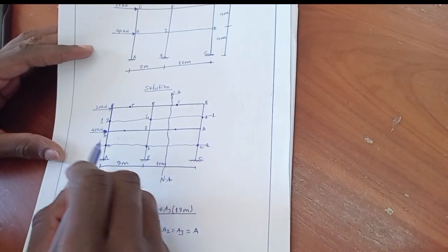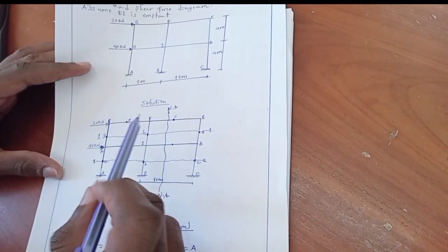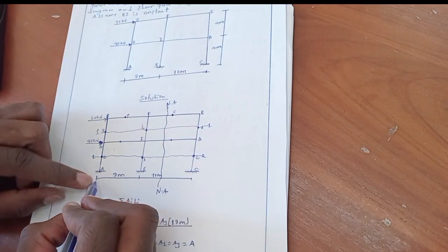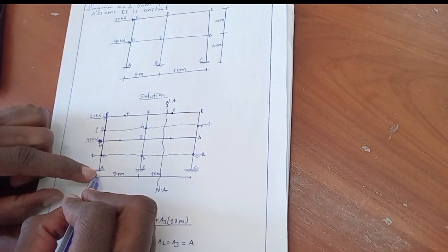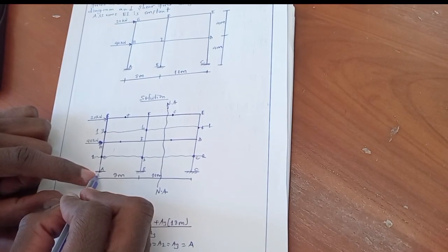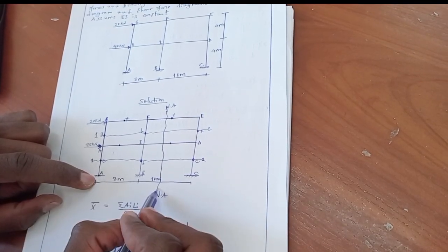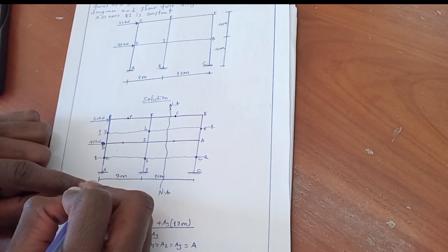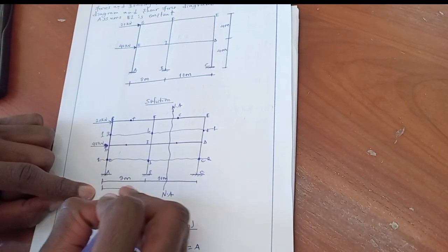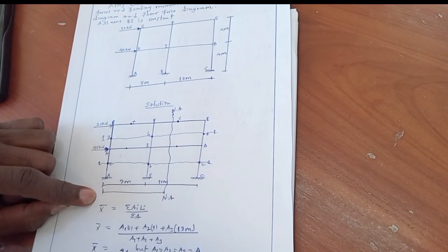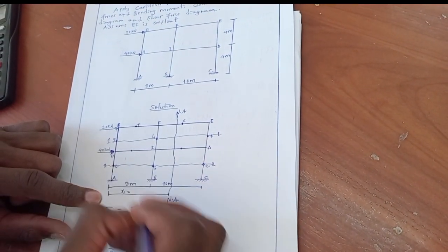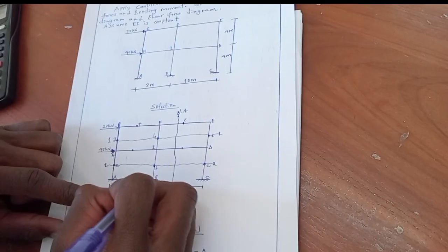Since Cantilever method states that normal forces are directly proportional to the respective distance of the column member from the center of the column area, the distance of this column member from the centroid, let's say this is x1, is 8.67 meters.